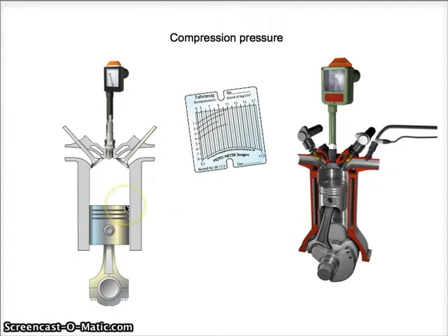We also have the compression pressure. It's something different from the compression ratio. The compression pressure is measured by installing a pressure gauge inside the cylinder, through the spark plug or another connection like an injection nozzle or something, and then the engine is cranked and the pressure is measured. And that's typically used to diagnose if the engine is in good condition.